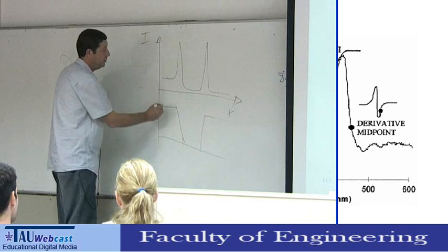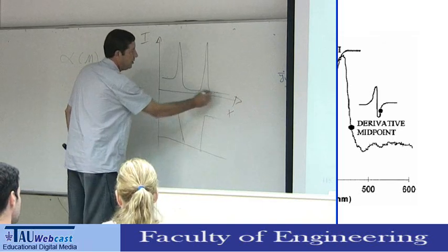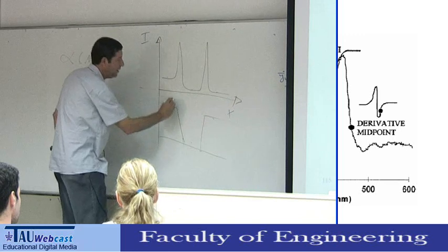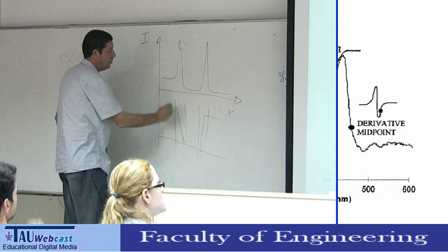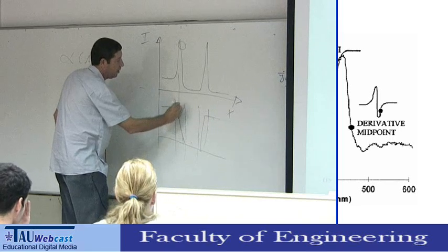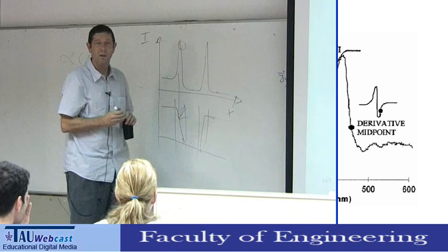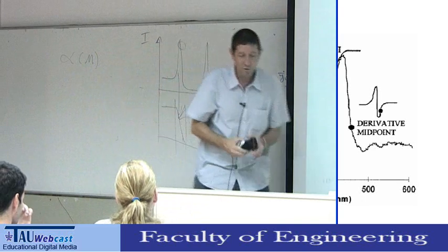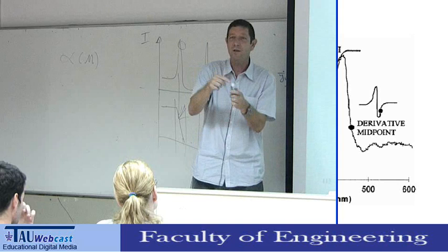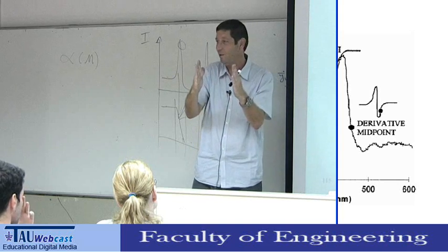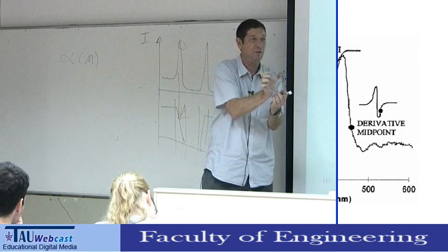And we got here certain emission, here certain emission, here certain emission, but on the sides of the photoresist we get much better scattering because here the electrons are emitting a lot of secondaries. So one of the issues of using electron beam to measure line width is that it is actually much more sensitive to the sides of the image than the actual image itself.